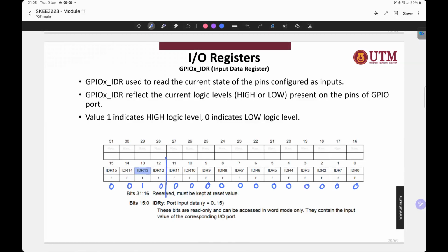And then by using the 8421 method, you need to find out the value. The value will be 2000, and above here also 0, everything will be 0. So this is your masking value. Actually the masking value will be 0x2000, or you can simply use 1 shifted to the left 13.